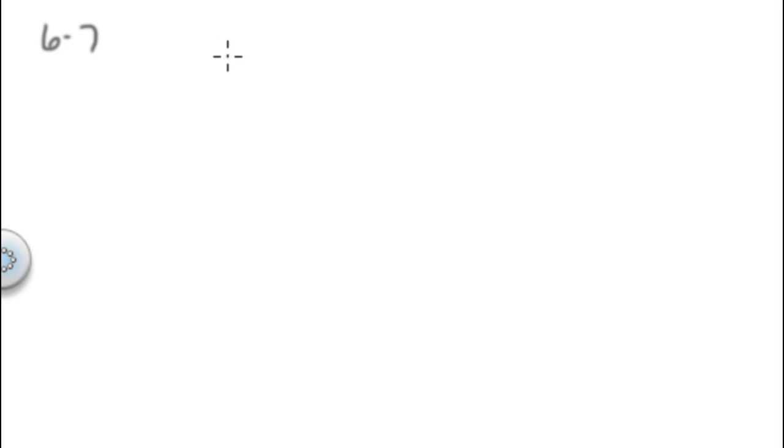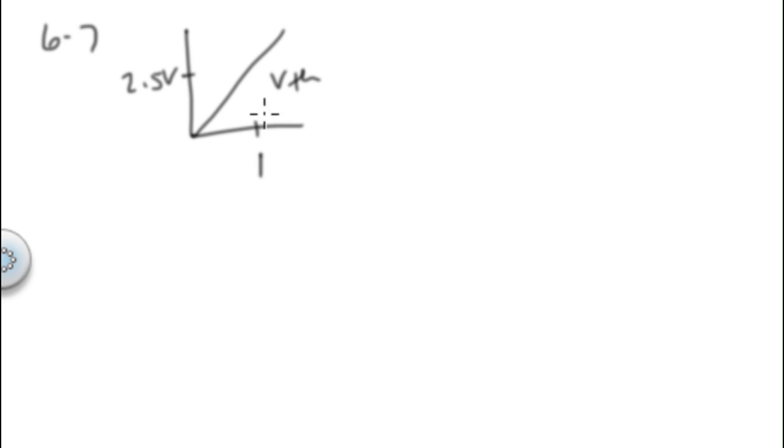So we basically say, okay, if I am going up at the rate of 5 volts per second, and I Thevenize it, I'm going up at the rate of 2.5 volts per second. So the V Thevenin would be exactly half. So at 1 second it would be 2.5 volts, 2 seconds it would be 5, etc., because the voltage splits exactly. And what would be R Thevenin? Well, it's 6K in parallel with 6K, or 3K.